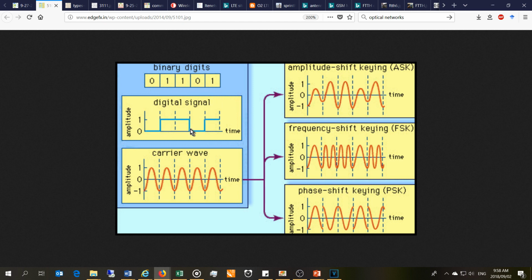Now if we're going to transmit this over the air, we might want to modulate it onto a carrier wave. There's the carrier. The carrier represents a high frequency wave. And what happens is when we merge these two together using a certain technique, it could be amplitude shift keying, for example. Can you see how the amplitude is changing, which represents the binary digits? So as we see here, when this thing would be decoded, because this is encoding, can you see when I put the digital signal on the carrier wave?